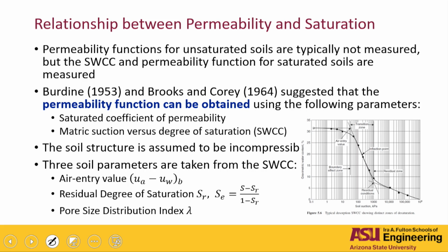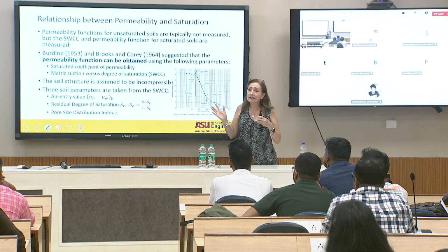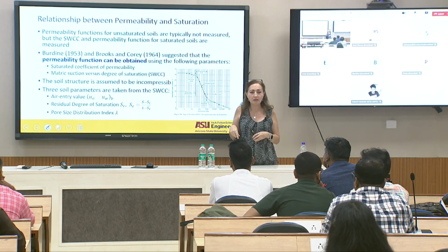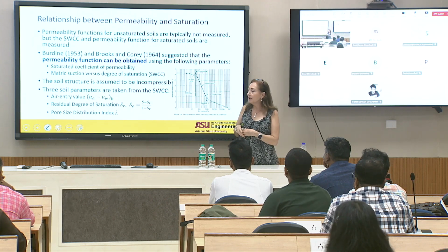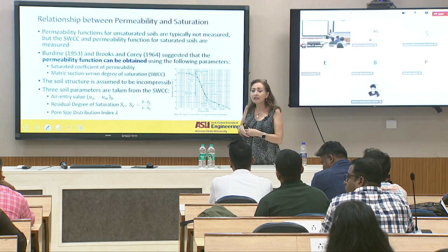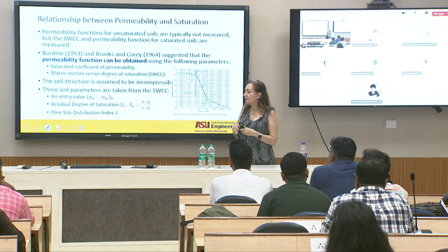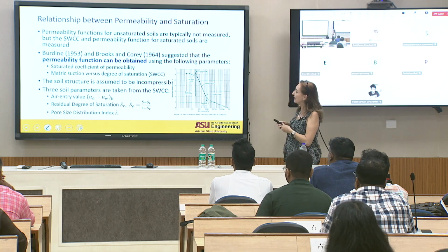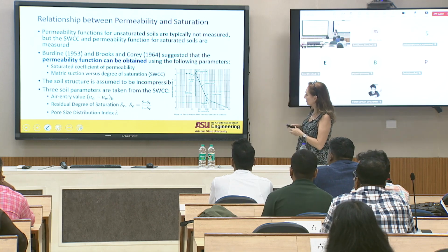Hopefully some of you are going to go out, in the field, and buy a soil-water characteristic curve device and try to just measure the SWCC or estimate it. And I'm going to show you some estimation methods as well, right? But if we have that one and a permeability value, we will be able to estimate the unsaturated hydraulic conductivity.